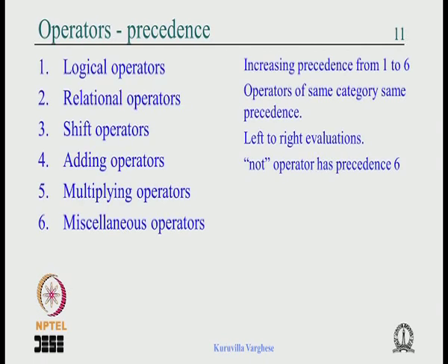So maybe we will stop here for today's lecture. We started with VHDL, how it evolved, what the basic context was. The Department of Defense had trouble with schematics, so it started with documenting, then was used for simulation and synthesis. It is human readable, works like a computer language, supports hierarchy, higher-level constructs, library-based design and so on. It is an open IEEE standard, so whichever tool or vendor, everybody uses the same language. And we have seen basically an entity and an architecture. Entity is the interface, architecture is the function.